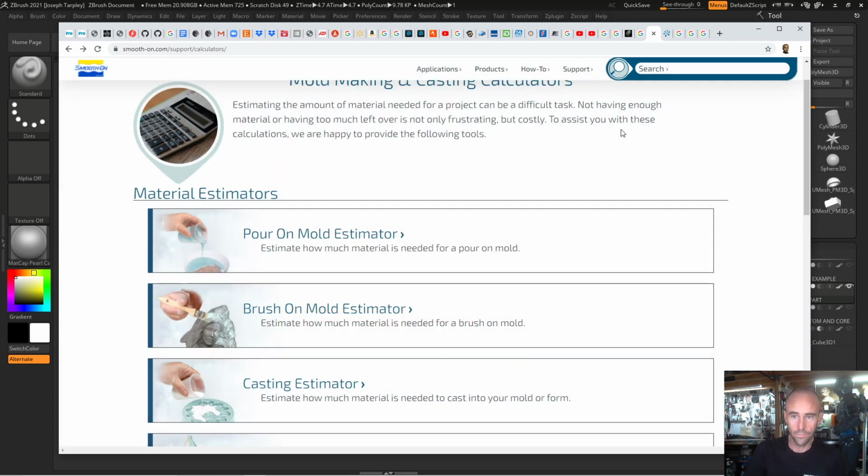I was working with an expanding foam, like I said, so I had to figure out for mine the mass of the volume of the entire object. Then I had to find out how much the foam that I was using was going to expand, and basically divide that with the amount of expansion to figure out the actual volume of the unexpanded foam so I could get my mix. Sounds crazy.